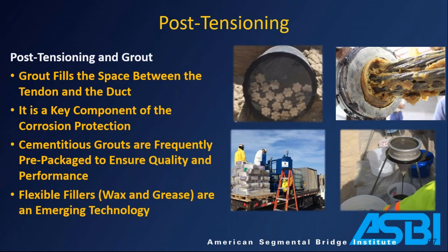Oh, not at all the last topic, is it? So post-tensioning and protection. I used grout. Grout is a kind of catch-all. Historically, grout has been used to fill the void inside the tendons and to give the tendon the protection against corrosion. So this is sort of a sawed-off cross-section here. You can see the gray grout. This is a good job on the grouting. You can see it surrounding all of the different strands and providing protection. No voids, everything looked great.